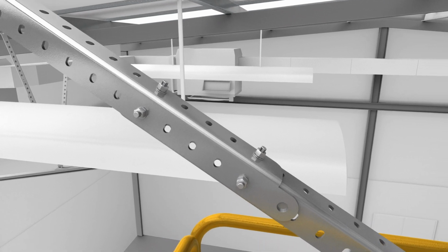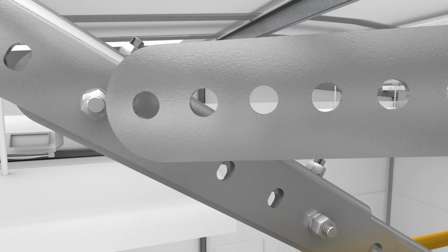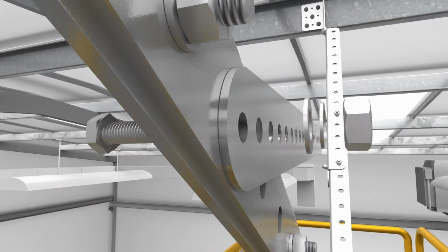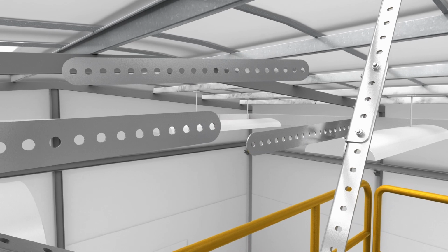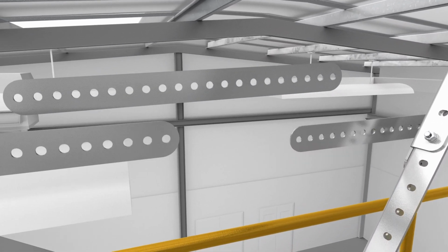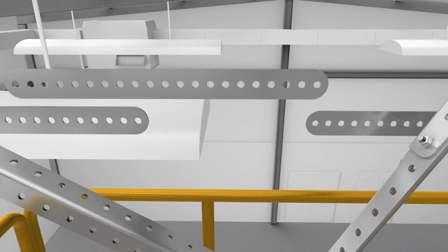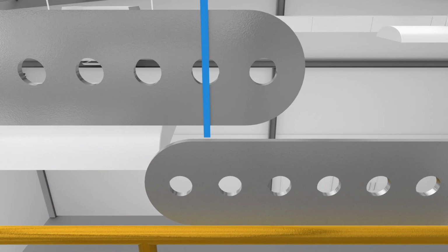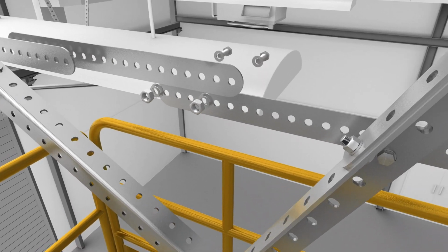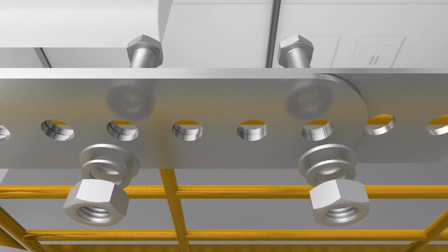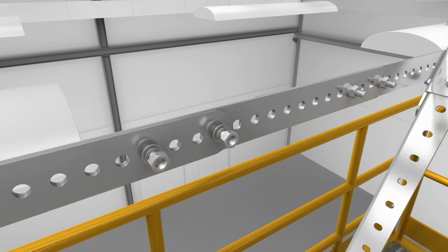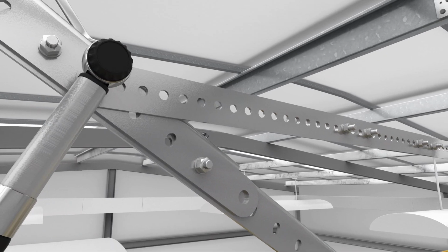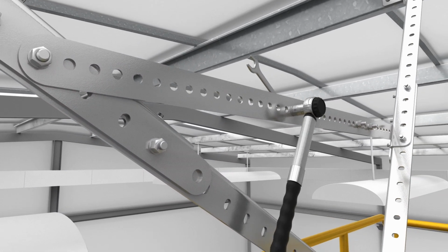Attach the hanger link arm braces to the hanger link arms using two M10 40mm bolt assemblies. Where bracing requires the assembly of multiple individual bracing components to achieve the specified total build length, ensure the braces overlap by a minimum of 2 holes. For all overlapping hanger link arm braces, a minimum of 2 M10 40mm bolt assemblies must be used per overlap to prevent rotation. Tighten all bolt assemblies to the torque value shown in the torque settings table.